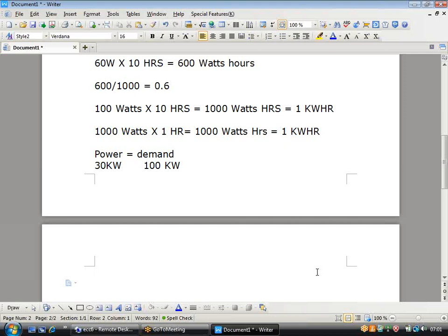Okay, but when you have a power meter, normally after you take the reading, we reset it. So that is one basic difference. Every month we take a fresh reading for the power meter and cumulative consumption data for the energy meter. So that is one basic classification: power meter and energy meter. What is a power meter? It measures the instantaneous power demanded in the supply line. But an energy meter measures the utilization of energy over a period of time, measured in kWh.